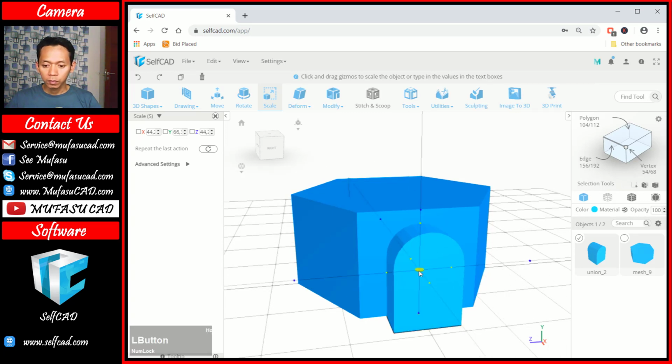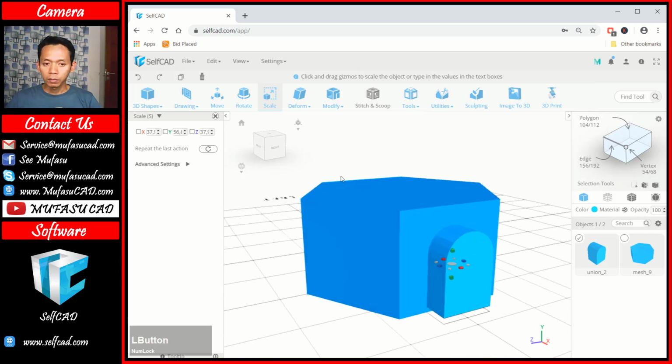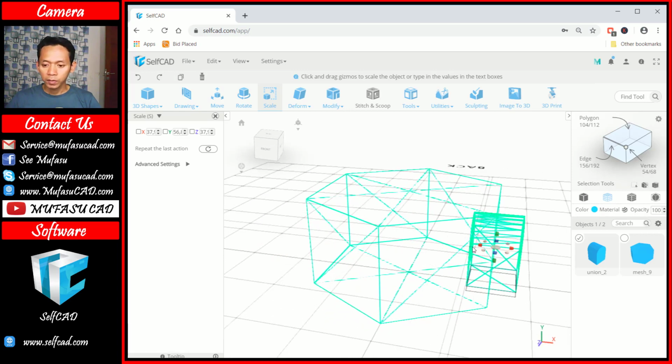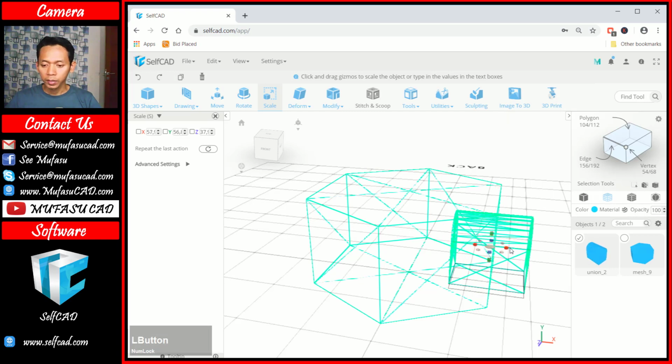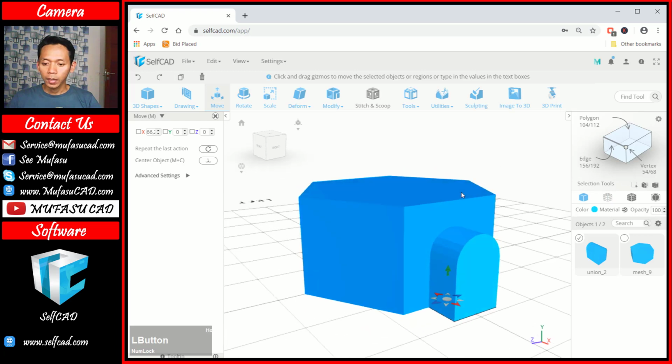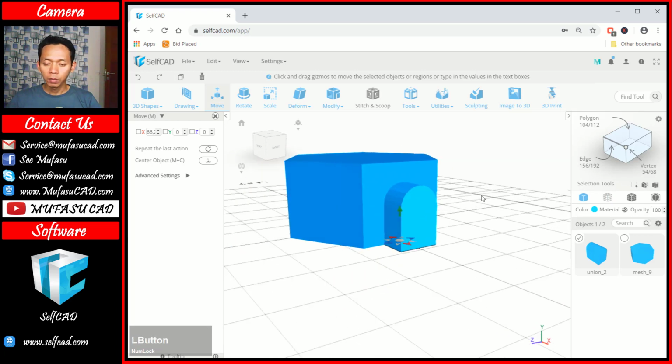Okay, I will make this point smaller, and next we can change to wireframe view. Okay, this is the wireframe view. I will scale in the right axis, and we can scale in the right axis here. Okay. You can use a move command to move it to the bottom. You can change again to mesh view, and I will duplicate these 3D models.